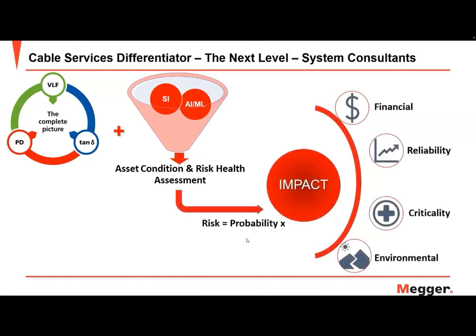But basically, we're looking at risk of failure, and also the probability of failure. Risk is the probability of failure multiplied by the impact of failure. This means that the total amount of risk exposure is the probability of, let's say, the fault occurring multiplied by the potential impact or the damage incurred by the event. And that impact could be financial in terms of customer interruption costs. You certainly have replacement decisions, and you've probably got some collateral damage costs that are financial. We talked about reliability indices, safety, SAIDI, CAIDI, CMI. That all gets affected, and that has an impact to the utility.